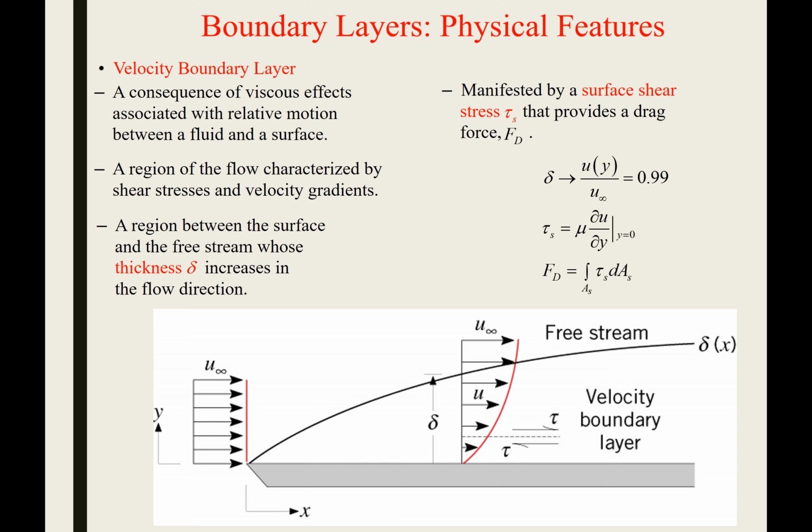If I'm holding the fan here, maybe a few feet away from the table, and it's a really big fan with a big cross-sectional area, let's suppose that I can create this really nice uniform flow. So that flow is going to be coming at a u infinity, all at a nice uniform flow. Then when it encounters the table, what's going to happen in terms of the velocity profile of our flow? If it's just this nice uniform flow before it hits the table, it'll be constant with respect to y, which would be the distance from the height of the table.